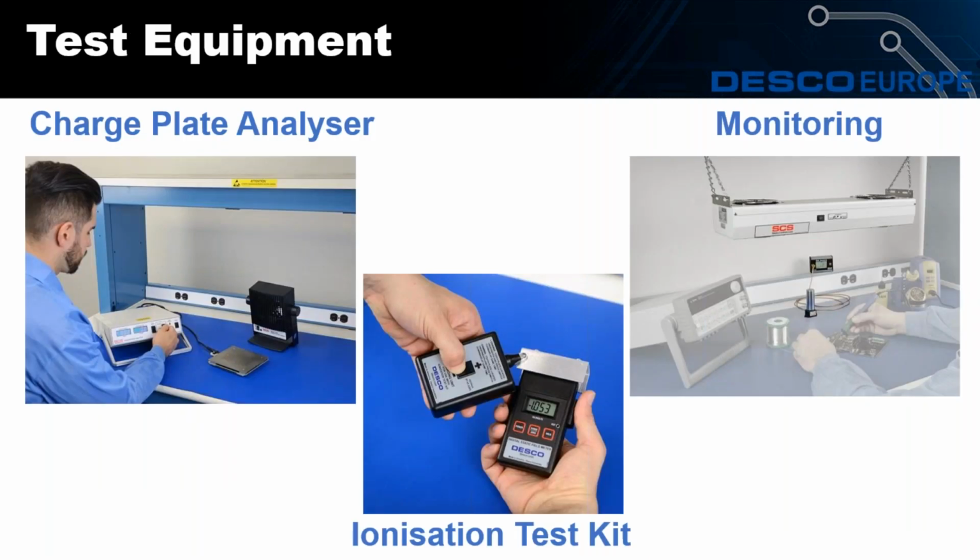Going back to the question that was asked and what Stephen was referring to, the standard calls for a full verification annually. To do that you would need to use a charge plate monitor, which checks for decay times and offset voltages. That's the annual verification, of which a record needs to be kept. But certainly, a year between verifications is a long time.